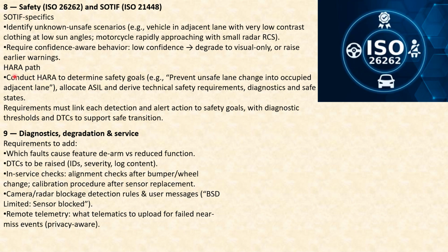And talking about ISO 26262, when it comes to the HARA path, conduct HARA, hazard analysis and risk assessment, to determine safety goals to prevent unsafe lane change into an occupied adjacent lane. All right, and allocate ASIL and derive technical safety requirements, diagnostics and safe states.